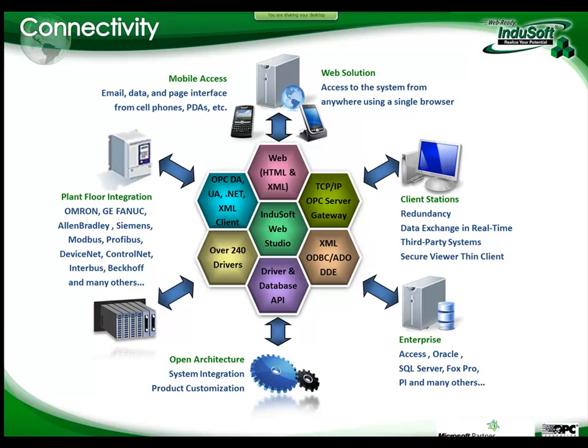Okay, if instead you have Siemens, we have the drivers for Siemens S5 or the S7 family, 200 all the way to 400, and even the new ones, 1200. We have the drivers for that as well. All the Allen-Bradley families, it goes back all the way from PLC2 to PLC5 to the ControlLogix family. And we can talk Ethernet, we can talk serial, we can talk DH+, to all these families. And the interesting thing is that this is all part of the InduSoft Web Studio product. You don't need to install anything extra to be able to communicate with all those devices.